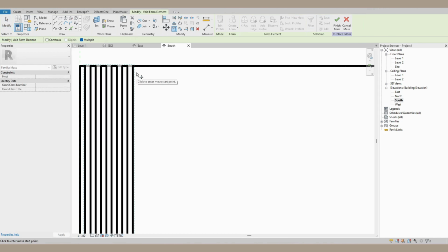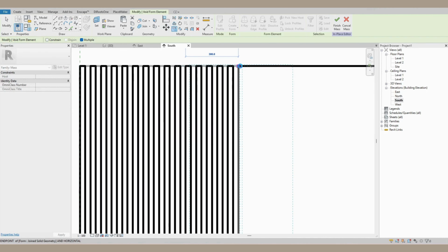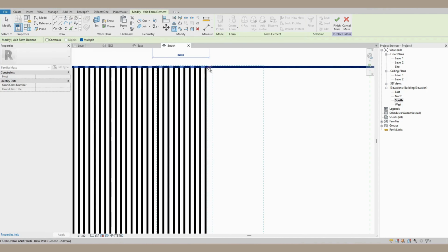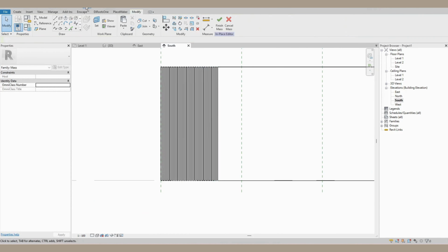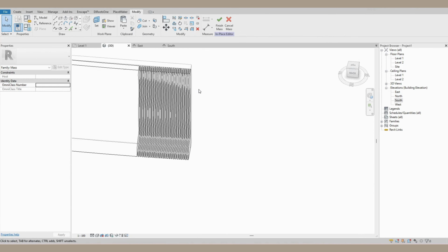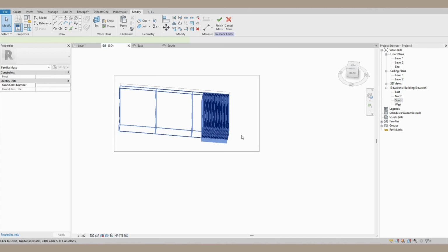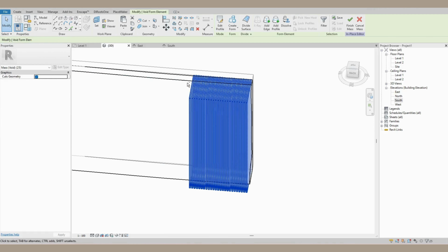Because as you can see, if you copy in this way, you're not selecting the input, and then you can go into your elevation view, and we're going to press CO, and we're going to copy from mass to mass. So by that, I mean, if it's a solid form from the beginning, copy to the solid form at the end as well, just so your line cuts at the same place. Keep checking on your 3D view if this is working successfully, if there's anything you want to change.